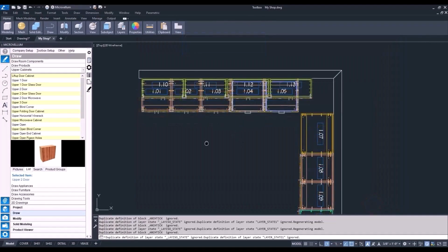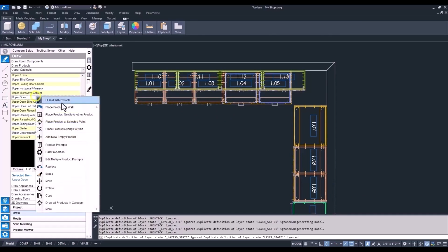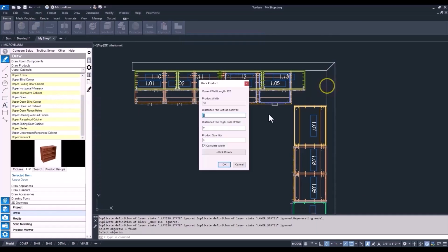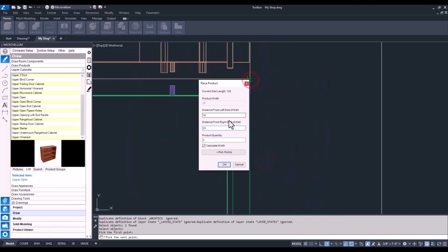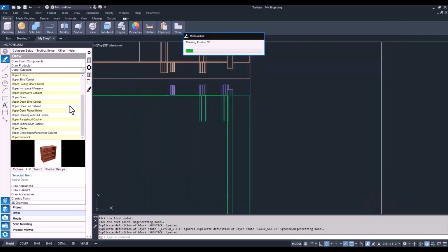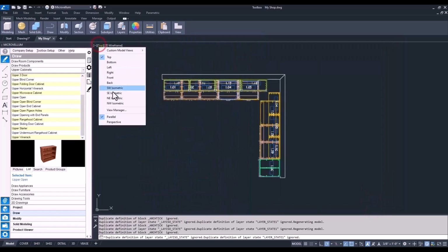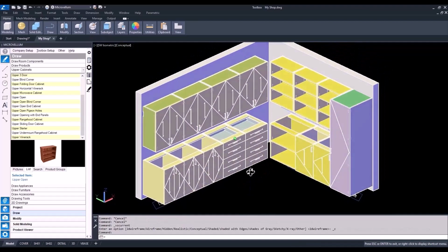Now for the next wall, doing the same thing, but for the right side, we're going to double click in there. Make sure we give ourselves a distance, so we're stopping it before that tall cabinet. Like your quantity, we'll leave that at 3. That looks good at 27 inches each. Take a closer look at it, see what else we need to do to finish this up.